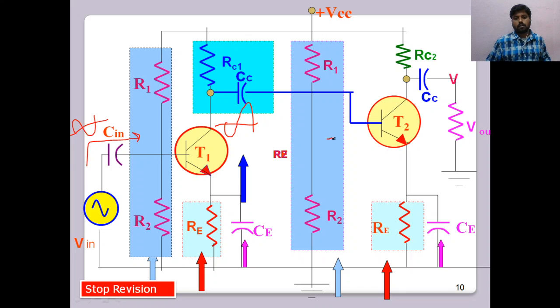So as you apply this out of phase signal to the base of the second stage, you get again a 180 degrees phase shift, so the output will be like this. It is an amplified version of the first input signal, but here it is 360 degrees out of phase. That means 0 degrees phase shift.